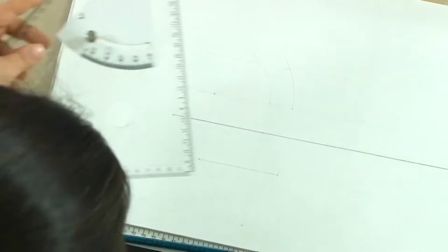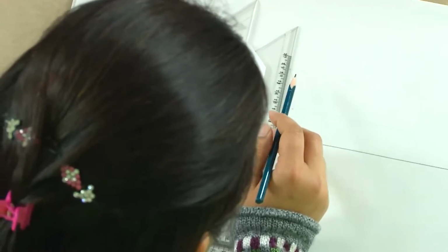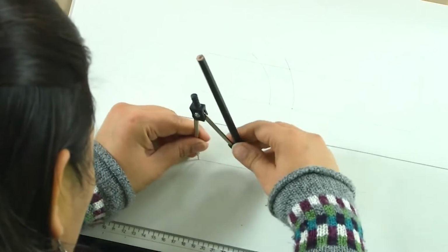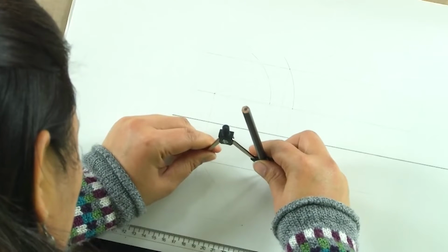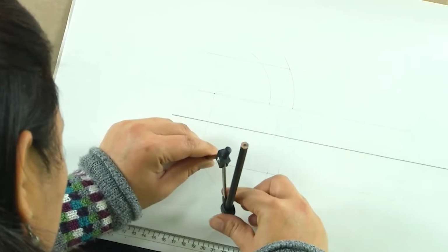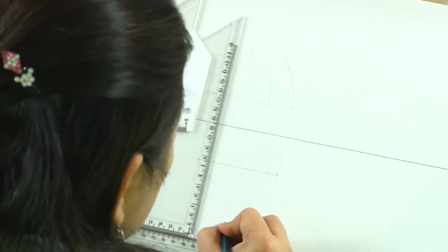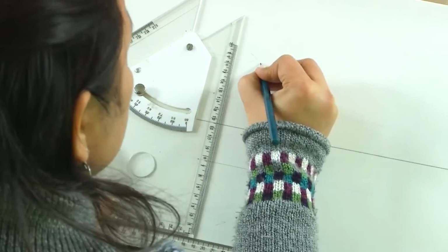And we can also do the reverse. We can take the projection of the front elevation onto the top view and see where it intersects. So, I am doing simultaneous drawing, but if you see, this is the point and this is the point here, which ideally should match